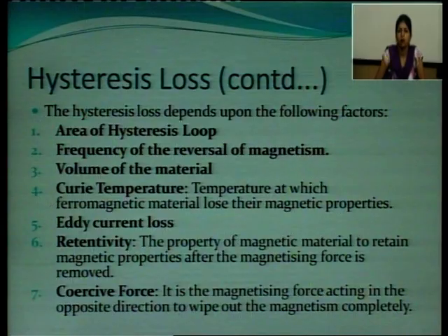So, the hysteresis loss depends upon the following factors. First is the area of the hysteresis loop. More the area of the hysteresis loop, more is the hysteresis loss. Second is the frequency of reversal of magnetism. Greater is the frequency of reversal of magnetism, greater is the hysteresis loss.